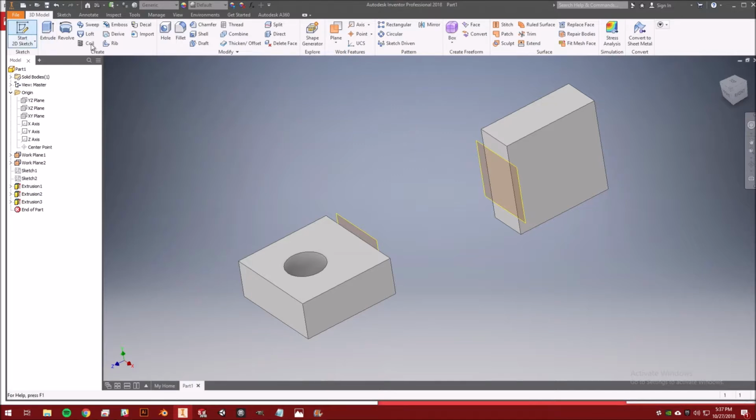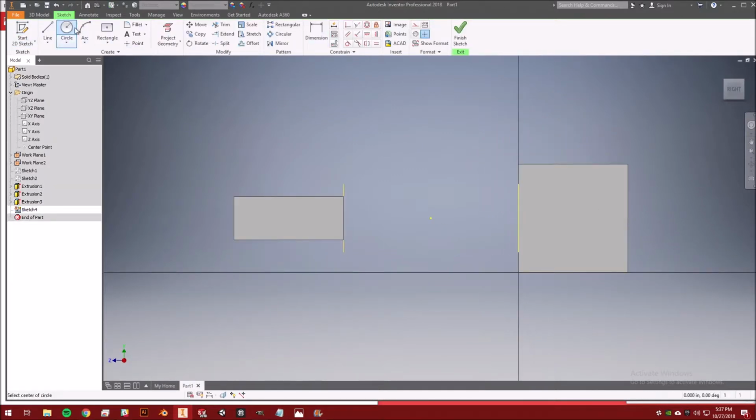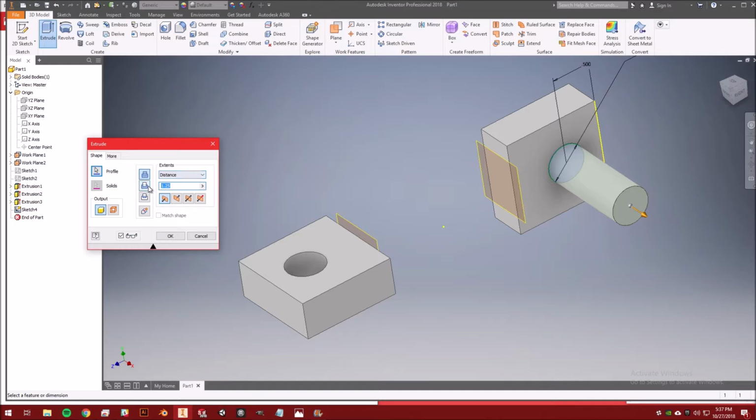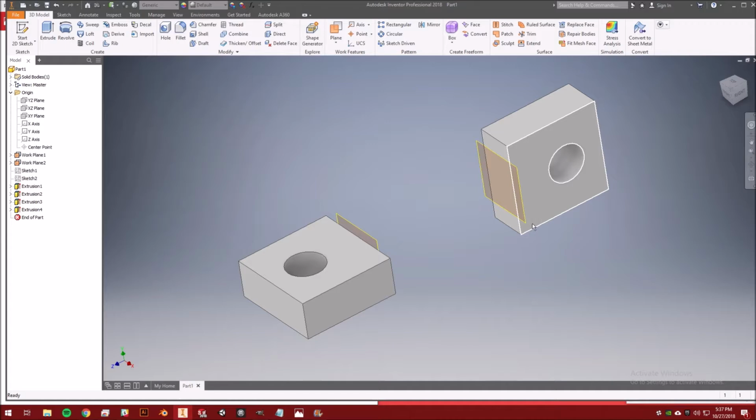We're going to do the same thing for the other half. And you'll notice what I'm doing to get the hole directly in the center is finding that green center point on this line here and moving it out so that this dotted line remains. That allows us to avoid having to put multiple dimensions on here. So this is centered vertically, and then we just have to make sure that it's 1/2 inch horizontally, and then change the diameter. Alright, and next we will do the same thing. Make sure it's a cut, 2 Next, hit OK.